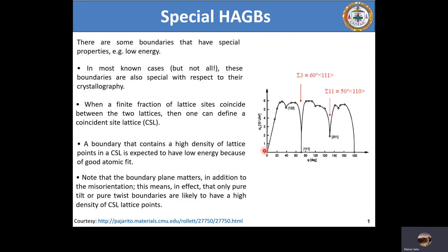But then, looking at them from the macroscopic point of view, we can say very clearly that they may be continuous with each other. But definitely, as I will show in the next slide, there is hardly any chance of a perfect coincidence of the lattice planes between the two grains, and that is what defines the 3 microscopic degrees of freedom that I have again mentioned in one of the previous sessions.